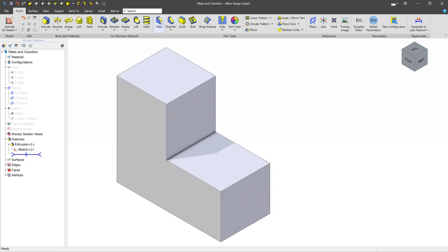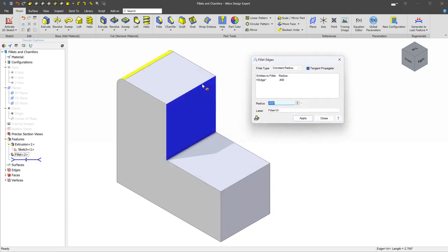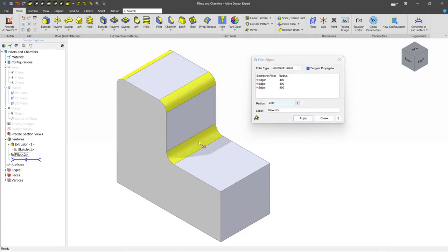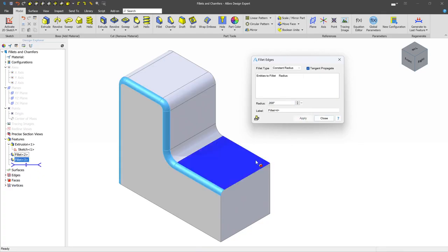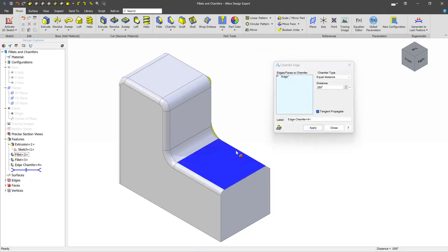Now, just a few words of advice as we close out this video. You'll want to make sure as much as possible that chamfers, especially complex chamfers and fillets, typically happen towards the end of your design. The reason is because when you make a chamfer, it ends up touching a lot of geometry. It modifies a lot of different faces, typically speaking. And the result of that can be, in some cases, that downstream things may mess up. So if you put fillets and chamfers more towards the end of the design, when it's in its more final state, than towards the beginning, you can keep that to a minimum and really ensure that your model is as bulletproof as possible.